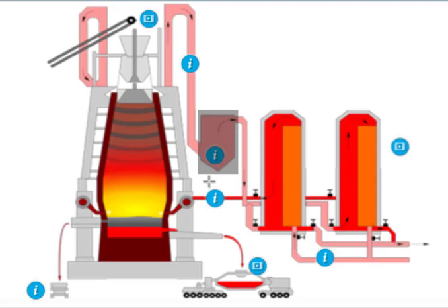The gas then flows through a scrubber, a venturi scrubber, which removes the finer particles, and finally we have a gas cooler where water sprays reduce the temperature. The gas will be hot but clean. Some modern furnaces are equipped with a combined scrubber and cooling unit. The clean and cooled gas is now ready for burning, so we can reuse this gas.